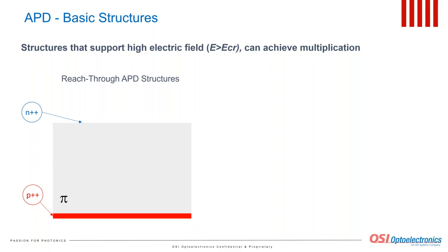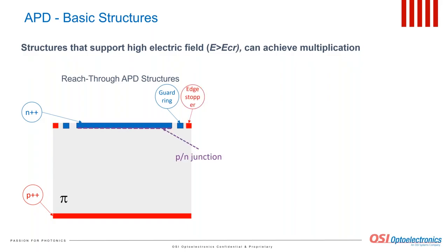We must create the guard rings and edge channel stoppers to avoid early breakdown and support high electric field across the whole thickness of the die. Moreover, to improve uniformity of the avalanche multiplication, it is to our advantage to create a dedicated avalanche multiplication layer, called sometimes P-well, with a moderate dopant concentration P+.